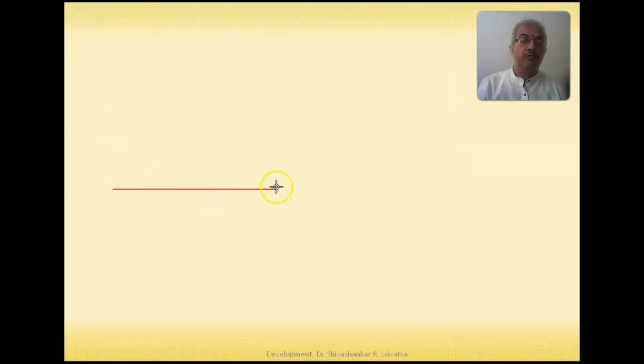We start with a normal line. Initially we should draw all lines that are thin lines. So you would introduce the XY, VP, HP. You need to draw the front view and the top.